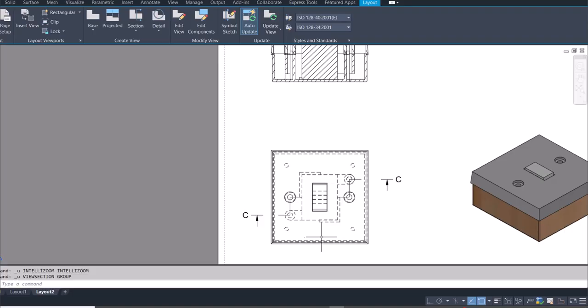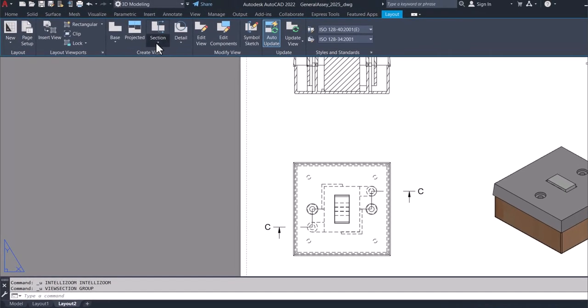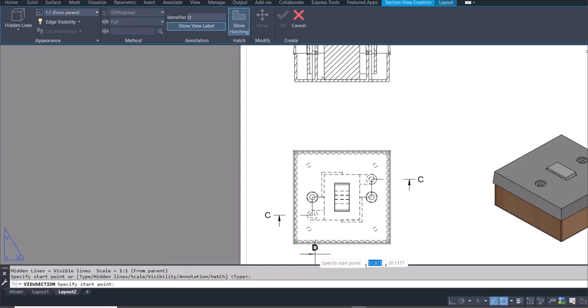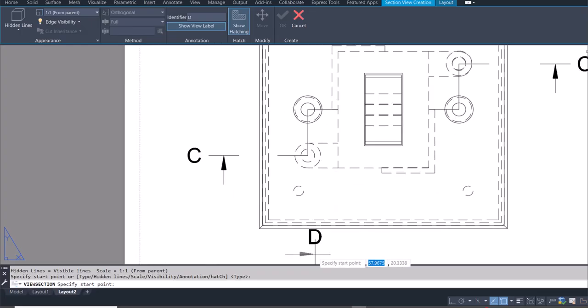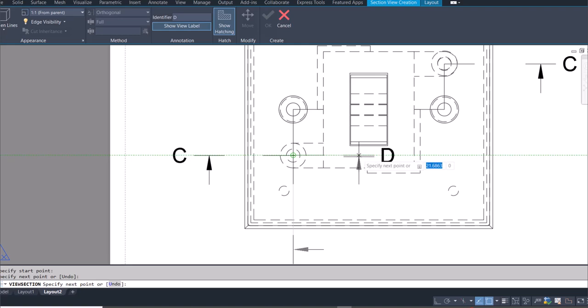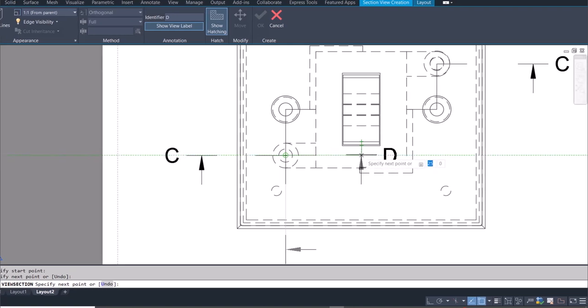Okay, so I am going to do another offset view. So I'll go for section and then offset, and of course I'm going through this. So I would track this point here. So click through here and then there, and I want to go through the midpoint of that.